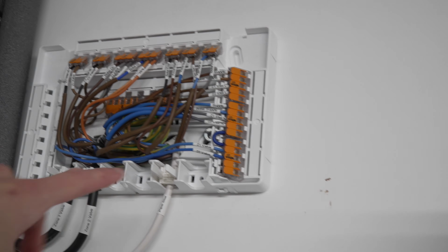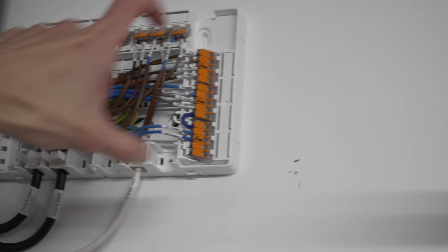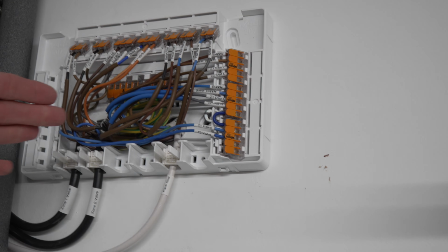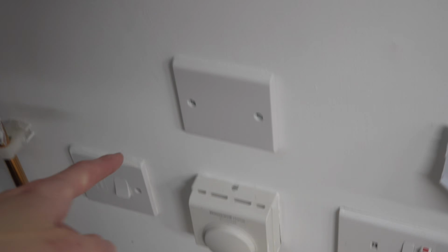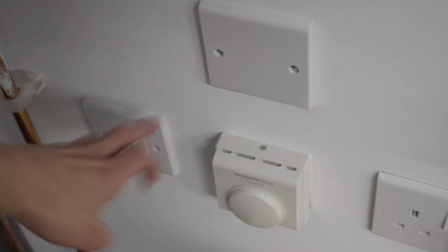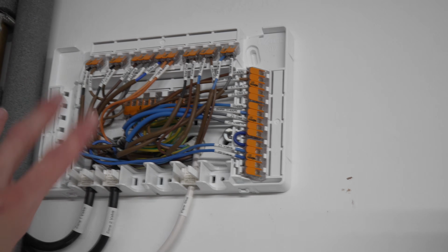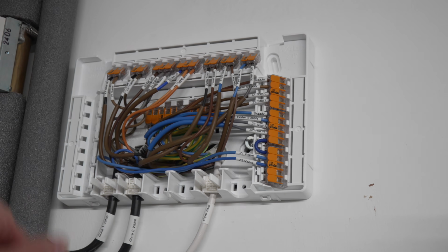Before I did this, what I had instead was the original wiring centre, which was just a back box with a blanking plate up here and a bunch of connector blocks inside it. That was some of the connections, but then there's additional connections made in the back of the thermostat and in the back of the spur. There's connections all over the place. So I redid it, brought all the wires back up to this wiring centre and put all the connections in one place to make it much easier to understand and diagnose.